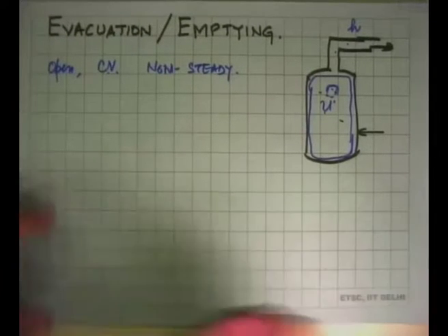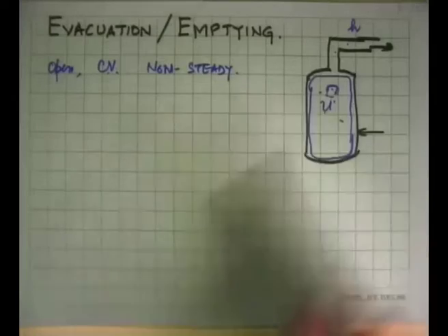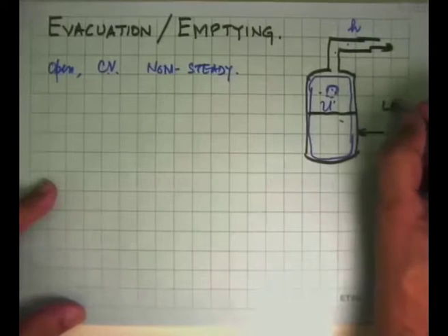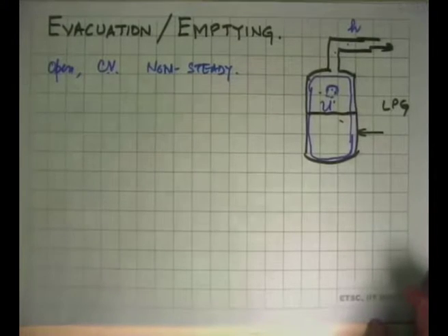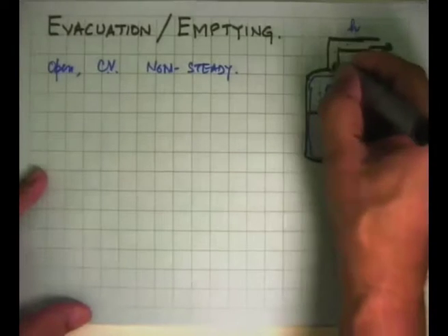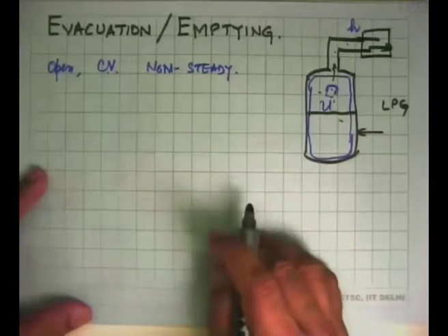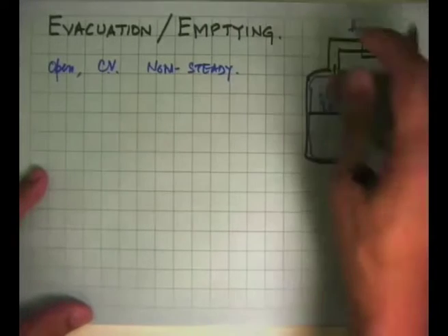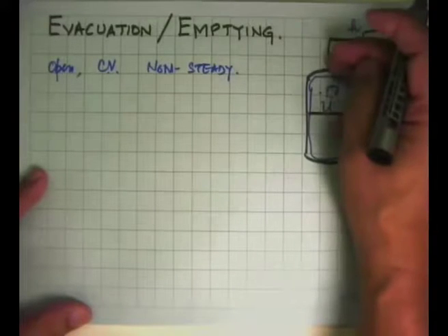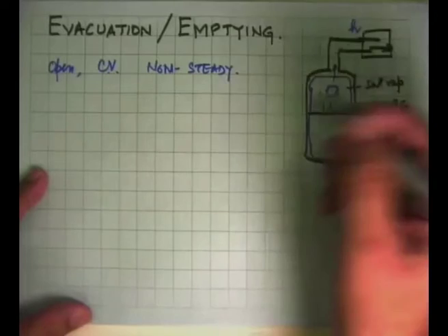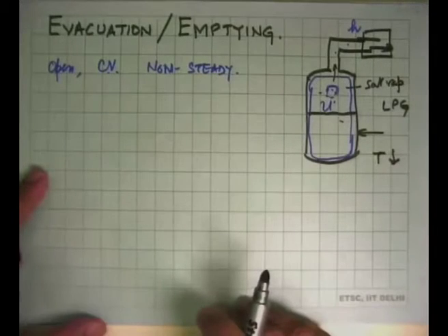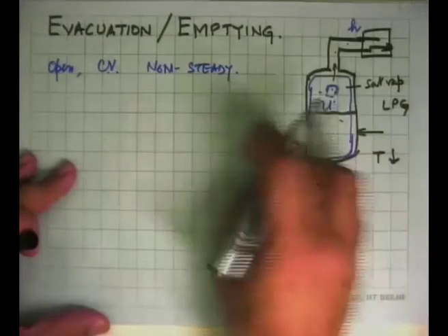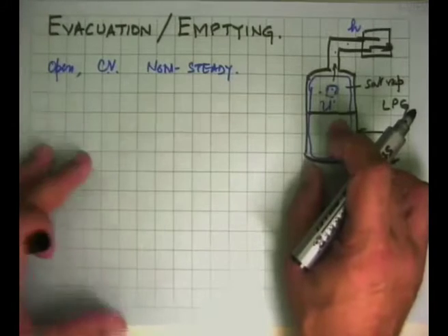In one of the assignments that I put, instead of just having gas or air inside this, I've given the example of the domestic LPG cylinder. What we actually do in the domestic LPG cylinder is draw gas from the top, and of course there is a regulator sitting on top of it. So you are drawing off only the saturated vapor. And as we keep drawing out, the liquid evaporates. You can do the calculation and see that the temperature inside keeps decreasing. But fortunately, in domestic cooking, we do it so slowly that we don't see this temperature drop. Whatever temperature fell, the ambient would supply energy and it would come back to the same temperature.